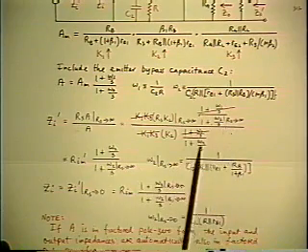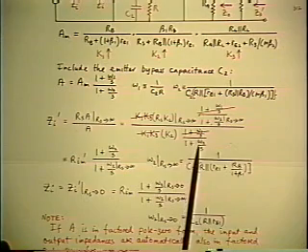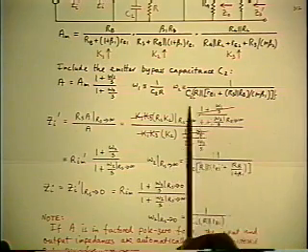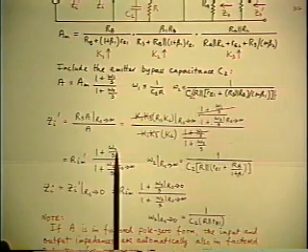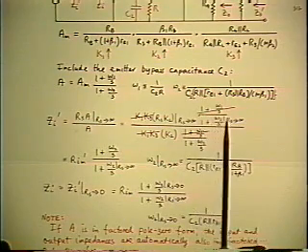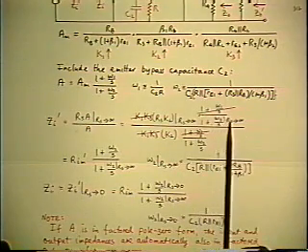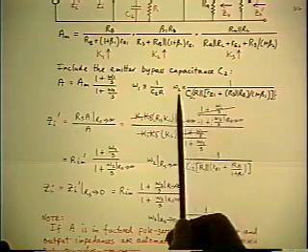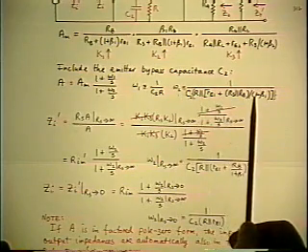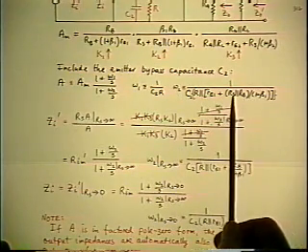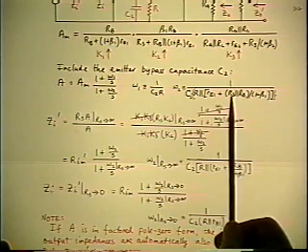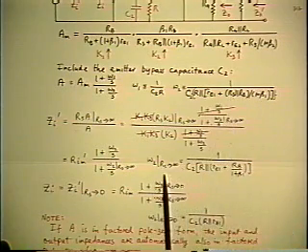So what happens? There's an omega 2 in the denominator that remains as is. That comes up into the numerator and stays. So the only new thing you have to work out is omega 2 as RS goes to infinity. But here's the original omega 2. If you let Rs go to infinity, it just takes away its paralleling effect.